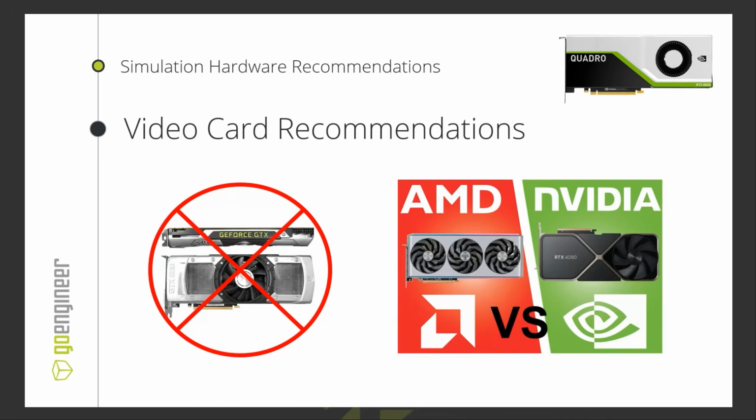Sure. All right. So when it comes to video cards, I am personally a fan of NVIDIA cards. I haven't used AMD video cards in quite a while, but AMD/ATI, they do make really good cards. When it comes to SolidWorks and SolidWorks simulation, you really want a professional grade or workstation grade video card. Now, what do I mean by that? With NVIDIA, that's your RTX graphics cards today. With AMD ATI, that's the FirePro. Versus the gaming cards, which are the GeForce and the Radeon cards. People say, well, can I use a Radeon card? Can I use a GeForce card? Absolutely. They will work for SolidWorks, but they're not recommended.